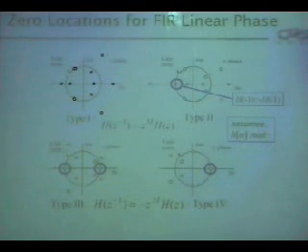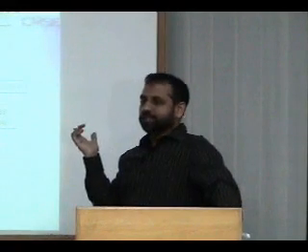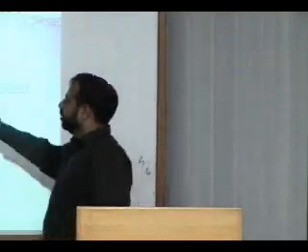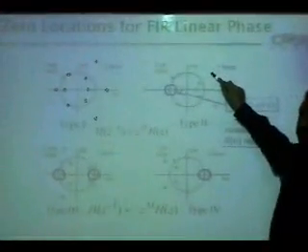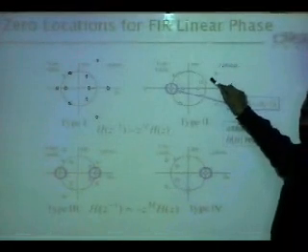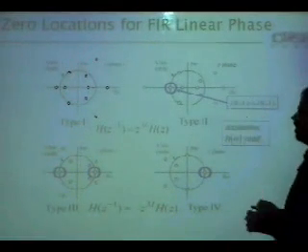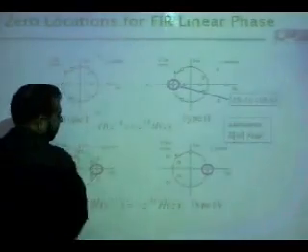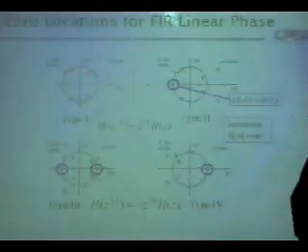Okay. So the linear phase FIR filters have all these 4 categories. No matter what you design, if you are using MATLAB to design, it will always design a linear phase filter. If you force MATLAB to design something which it cannot, either it will complain or it will not design anything. You still need to know these things. If you are forcing MATLAB to give me a high pass filter where m is odd, it cannot design that because of this reason. Right? Especially using the windowing method, which we'll study. So this is important, and that's what I have highlighted here.